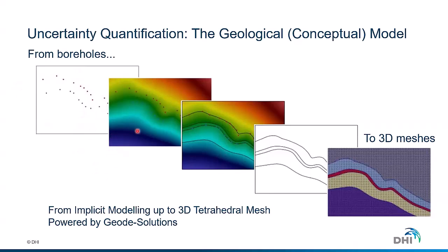Imagine this: we solve a system of equations, so we can consider the points as potential boundary conditions. Then behind the scenes there is a mesh. Each element of the mesh gets a value, what we call a scalar field. And when we have this distribution of the scalar field, basically we can extract any iso value that we require, so we can reconstruct the surfaces at the level that we want.